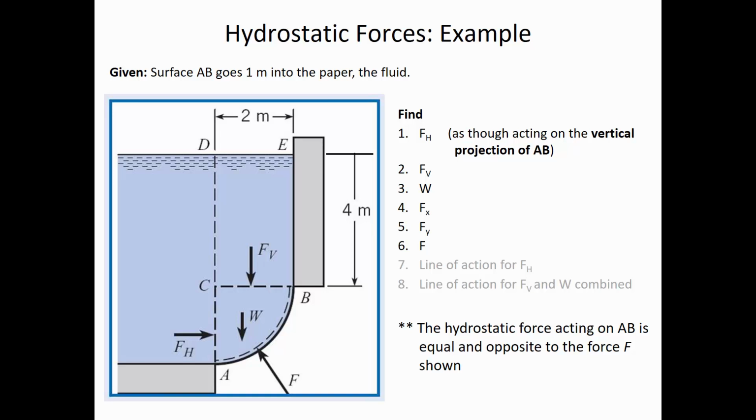And so there's this imaginary rectangular gate at AC that's the projection of the curved surface. If it's just a rectangular gate, that means that the centroid is half the way down. So it's here, this is the delta H, from the centroid back up to the water surface. All right, so rather than me do the calculations on the whiteboard, particularly because my marker seems to be dying out,